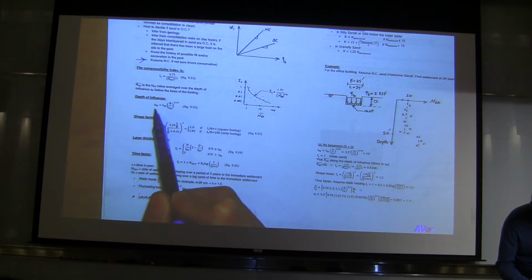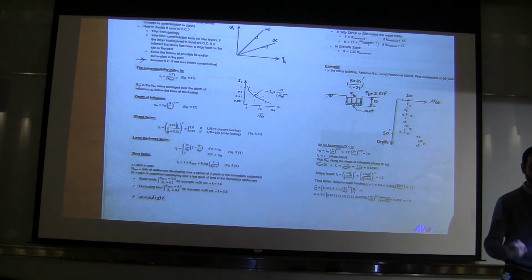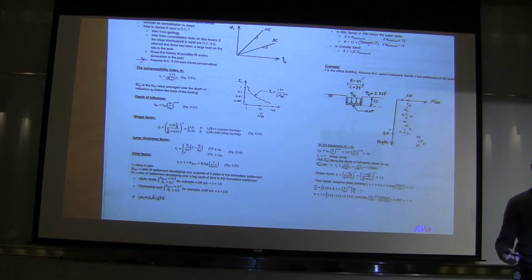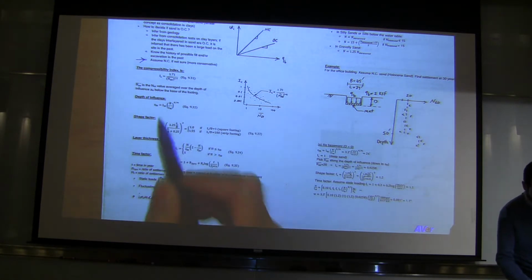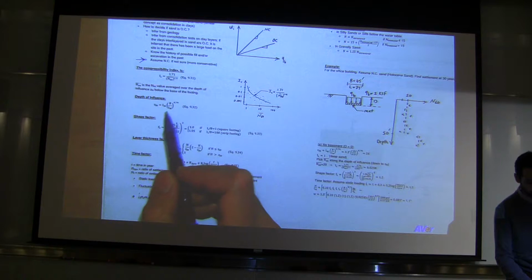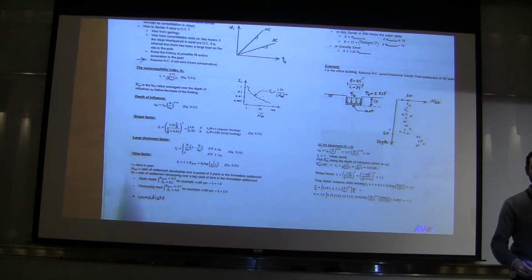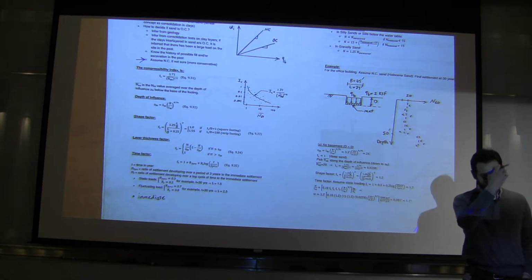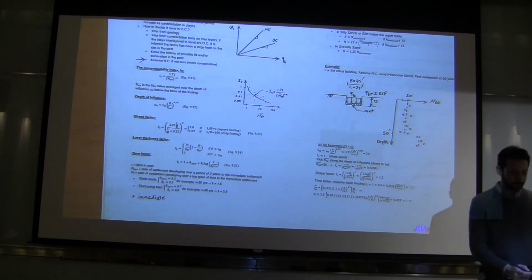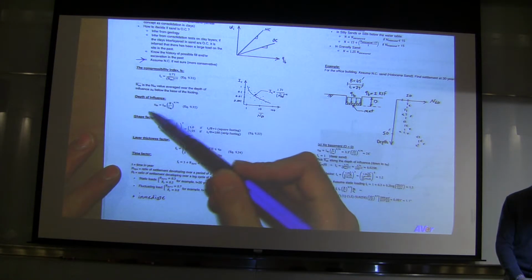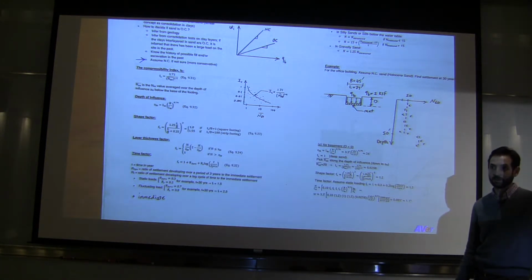So ZF0 is LR. Again, LR is there for units, so if you're doing it in meters, you can cancel out LR. It's dependent on B, the width of the foundation. It has that funky exponent over there, but don't get confused with the power function; it's basically related to the width of the foundation.